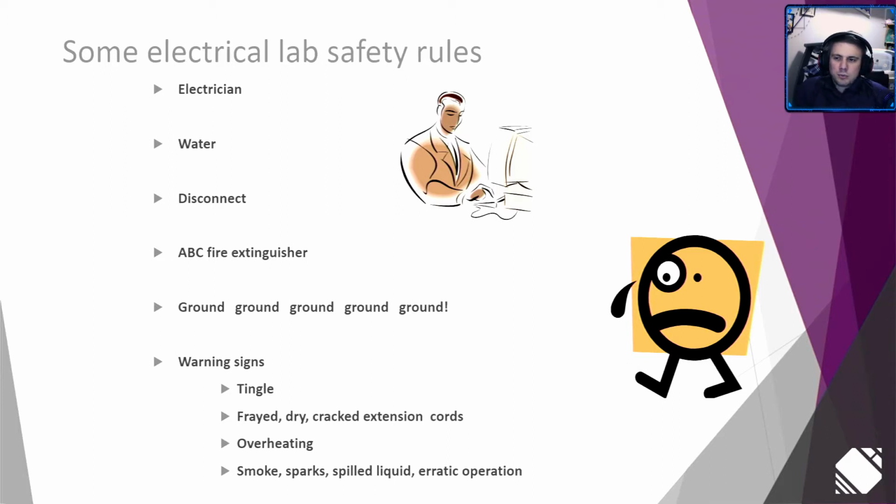if there's any problem in the inside of that complex system, you've still got a ground, because if you lose that ground, you can get a potential difference between earth, the ground that somebody may be standing on the floor, and the enclosure itself. So if an electrician walks up just to open the door, that potential difference can be enough to shock them and injure them. So we want to make sure any of the big equipment is double grounded, just as a protective measure.